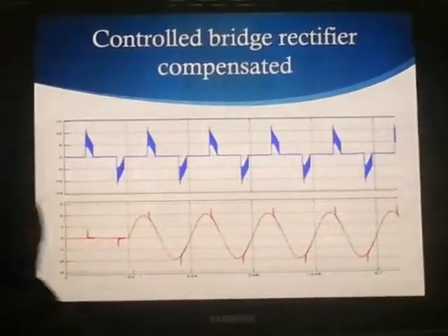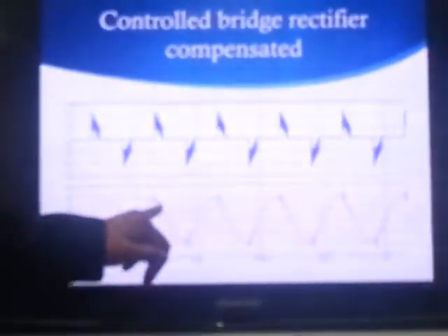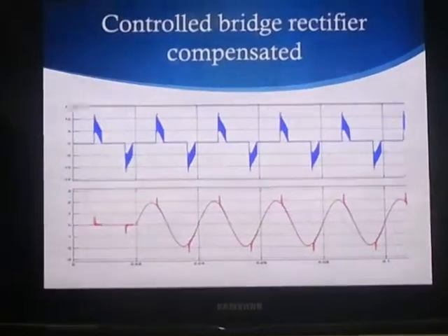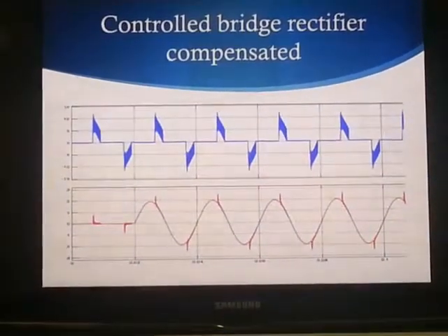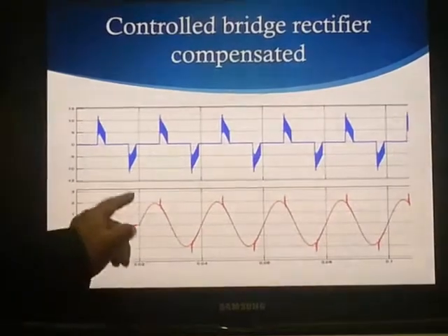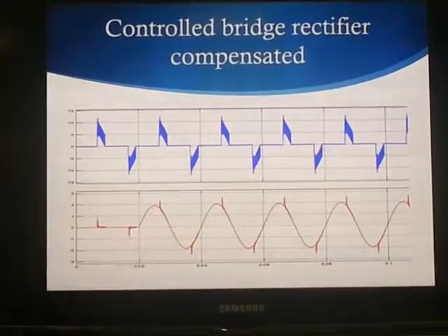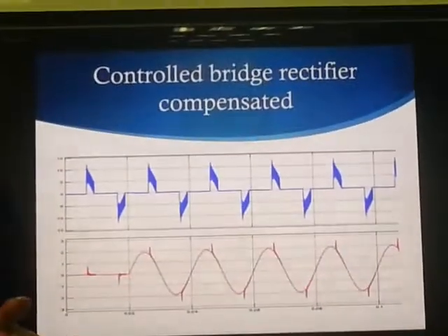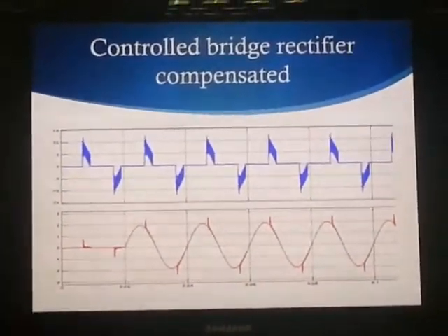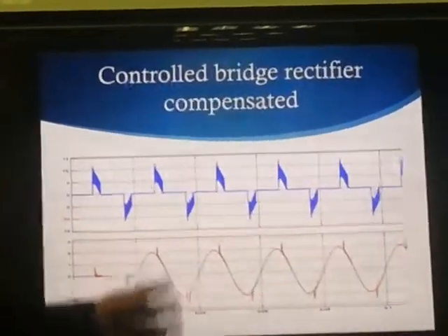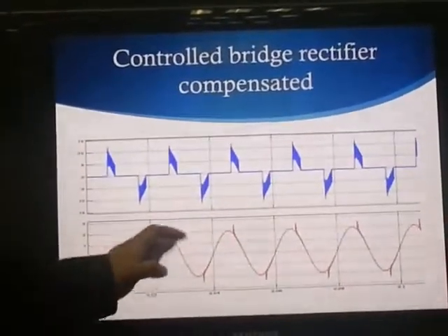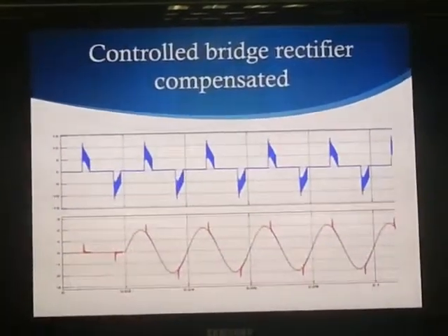The reason is because the system consists of inductors, and due to this L di/dt effect, we do have these spikes on the waveform, whereby the current in the inductors, as you are aware, cannot be changed instantaneously. Hence, we do have those decay periods, those waiting times for those currents to decay from the inductors. That's the reason we have got spikes.